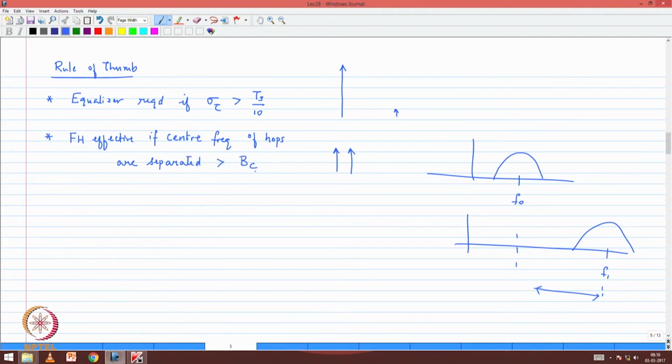And of course, why are we saying anything about the coherence time? Yes, you must be doing channel estimation. Channel estimation is needed whenever you exceed coherence time, when the duration of demodulation, channel estimation and tracking becomes larger than coherence time, because that's when you know that the channel has changed and therefore you must be adapting your channel estimates.